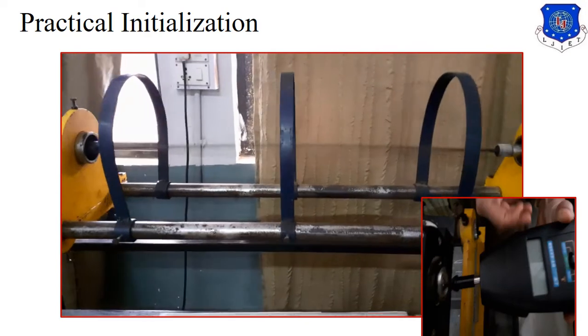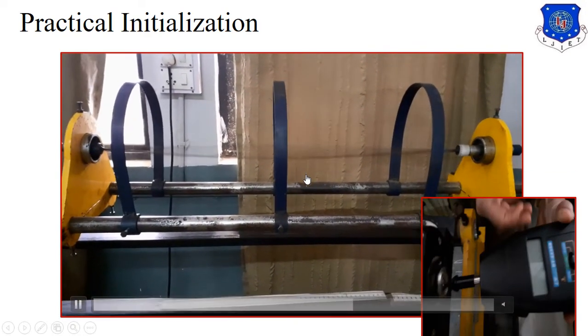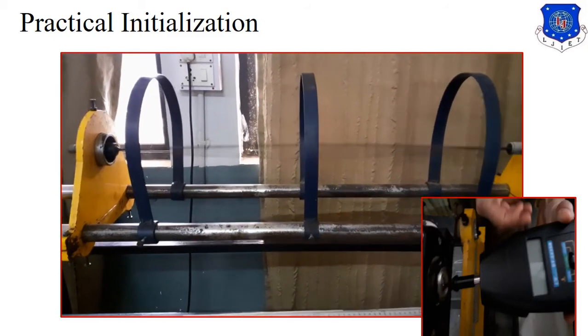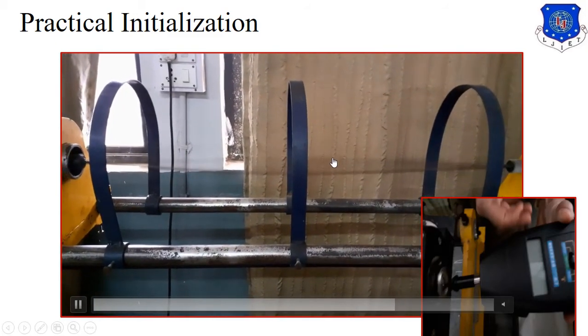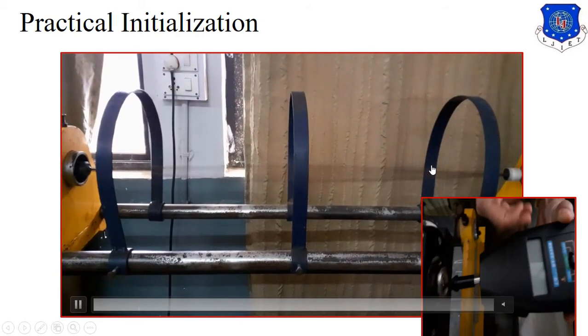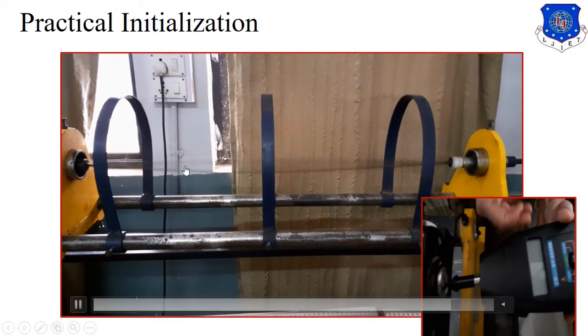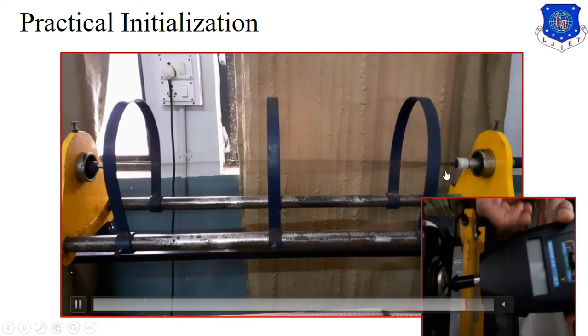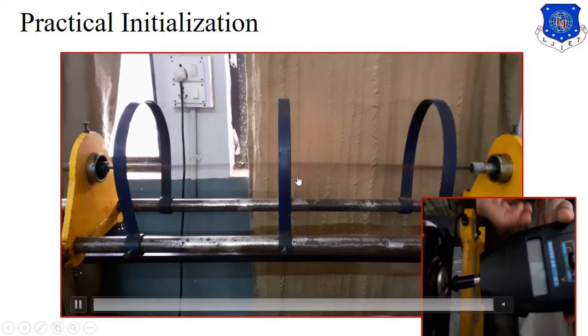If you see here, we are putting our system at the maximum speed, and here the whirling starts. We get the whirling of the shaft. Because there is a fixed bearing, we can see only a single whirl, and here we are getting the maximum deflection.